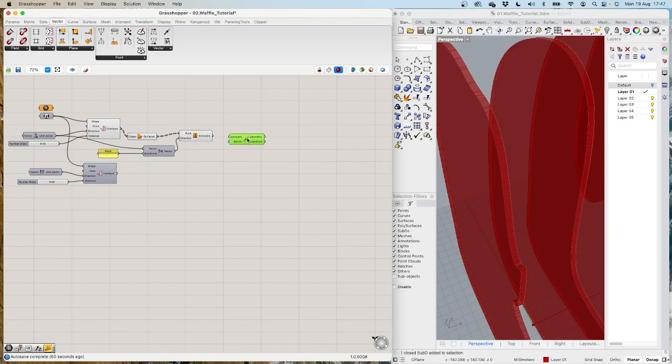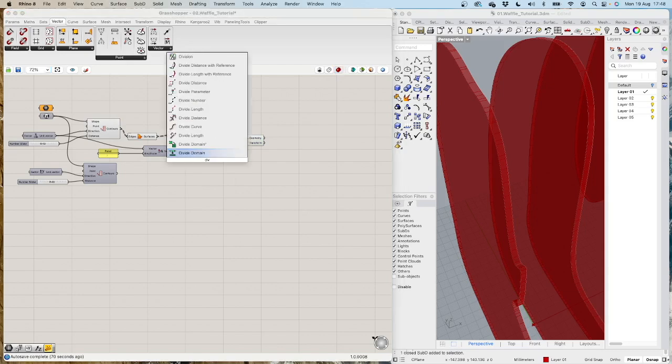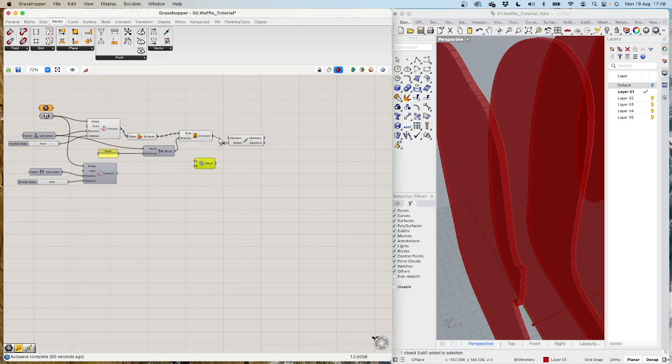So we have a move node, and I divide our amplitude by 2. So I halve that. Division. So I plug in my geometry, and I take my amplitude as a vector, and I take a panel and type in -2, half it.